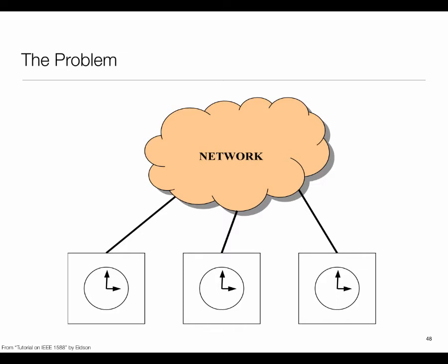If we were to recalibrate time very frequently, if very frequently we were to keep recalibrating the time, then it doesn't matter whether my local clocks were drifty or not. But in reality, you cannot resynchronize time very often. So what you do is you synchronize, and then you let things run on a local clock, and then again you synchronize. So the idea is that in most cases, good time synchronization also requires good frequency synchronization.